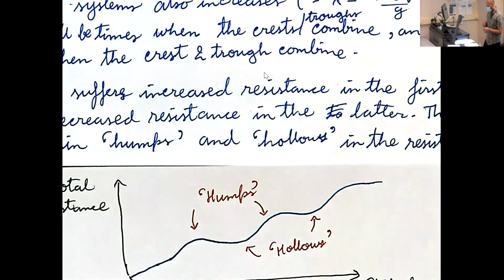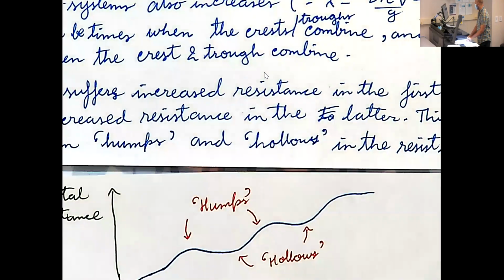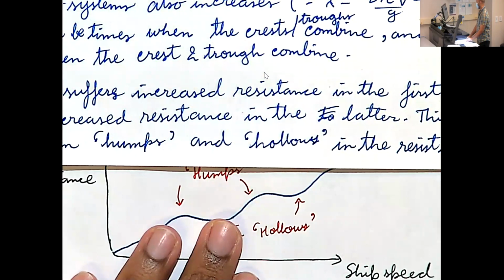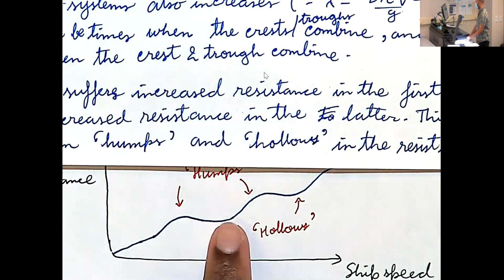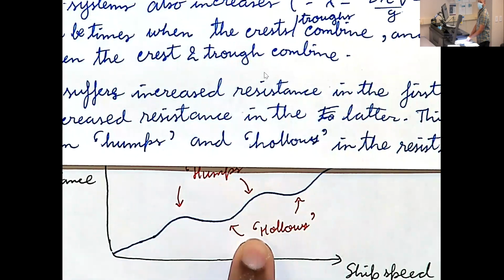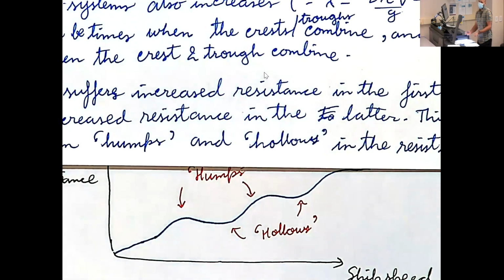Okay. So whenever you operate a ship, it's very useful to have this sort of curve handy. So you can decide, okay, I'm going, let's say 20 knots, I'm here. If I increase to 22 knots, I'll suddenly jump to here. Is it worth it to go faster? I mean, you go faster, but your power consumption increases substantially. Okay. So it's a trade-off.